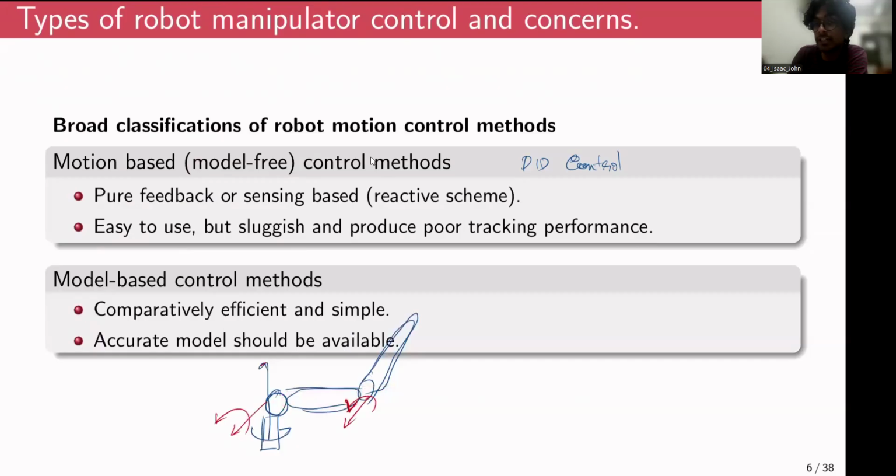If the inertia is low, we are only required to give a smaller control input to rotate about this vertical axis. And if it is fully stretched out, we would require a higher torque about this vertical axis to achieve the same rate of rotation, because the inertia is also very high.